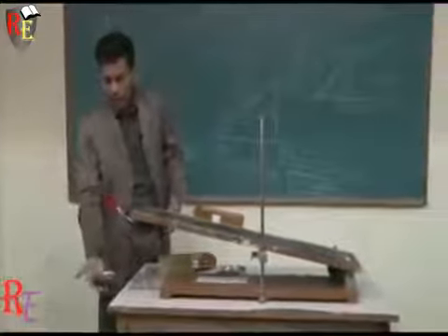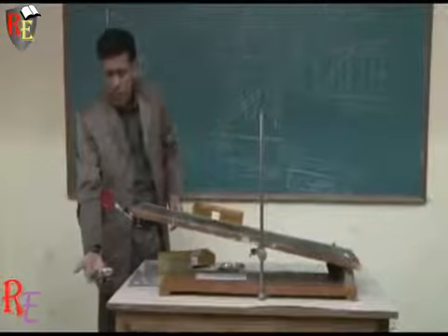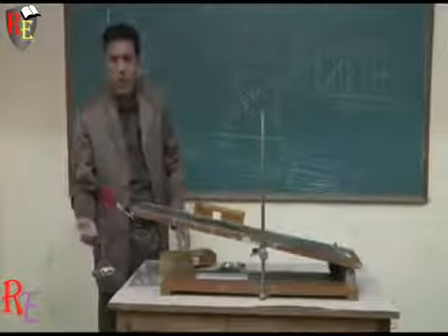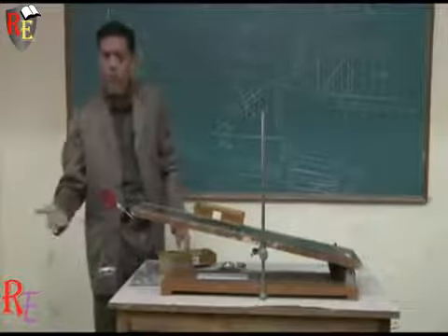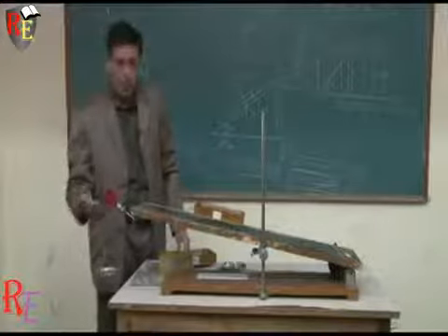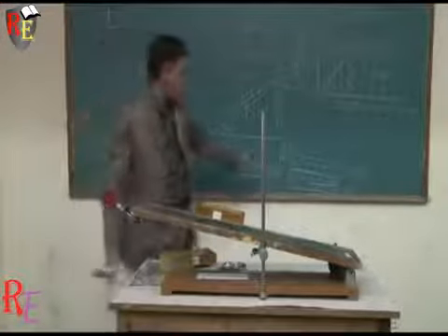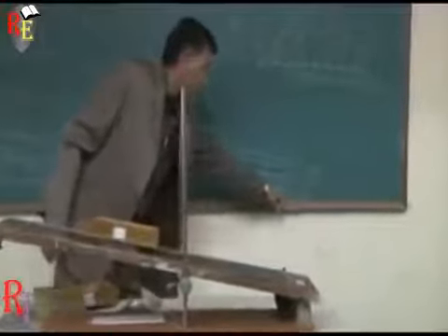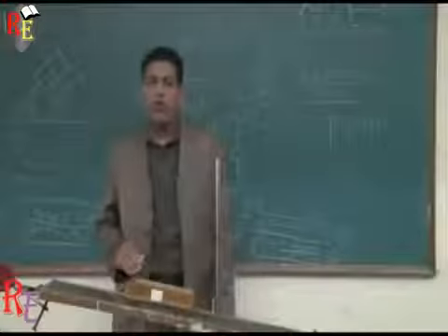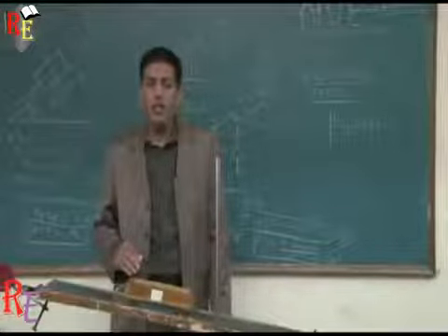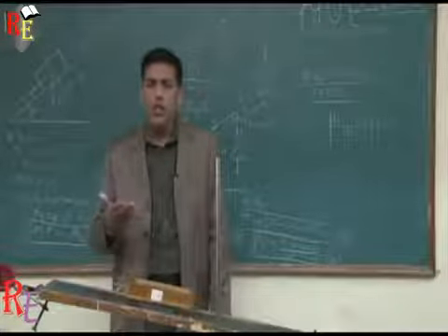And T minus P is equal to 0, or it means T is equal to P. The tension is equal to the load applied, P. So when I combine these two equations, then mu s dash is (P minus W sin theta) upon W cos theta.